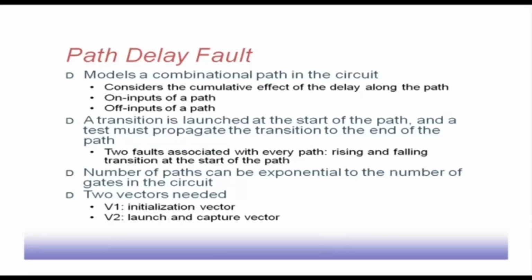So, that way normally this number of paths is going to be exponential to the number of gates in the circuit. So, we need two types of vectors for testing these individual delay faults. One is called the initialization vector, and the other is called the launch and capture vector. So the initialization vector will set